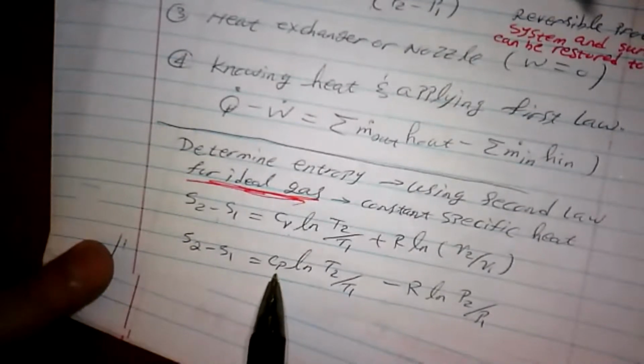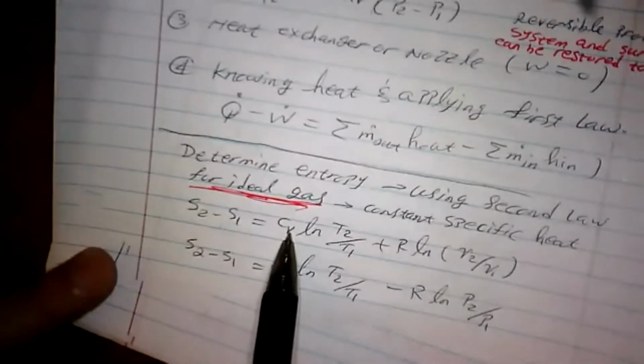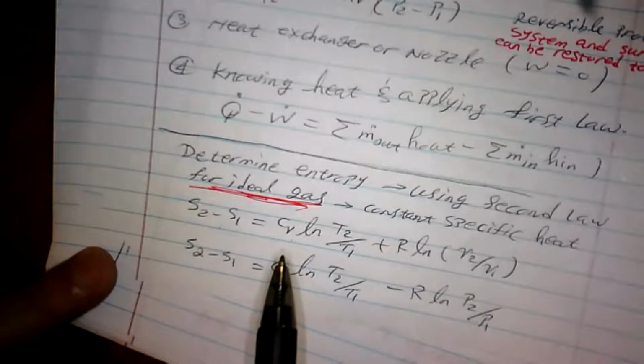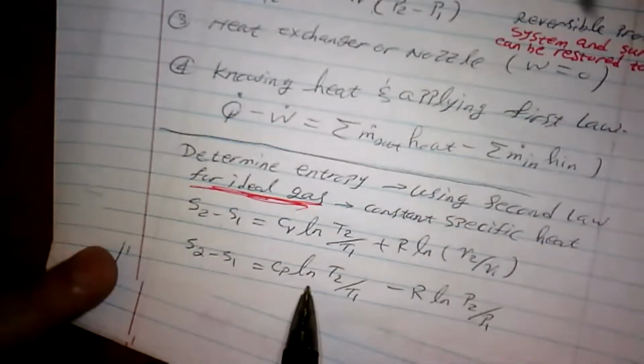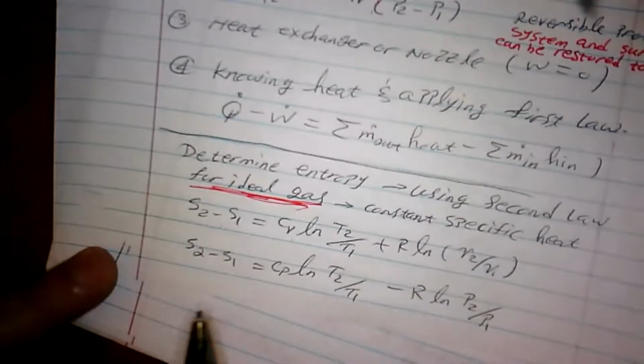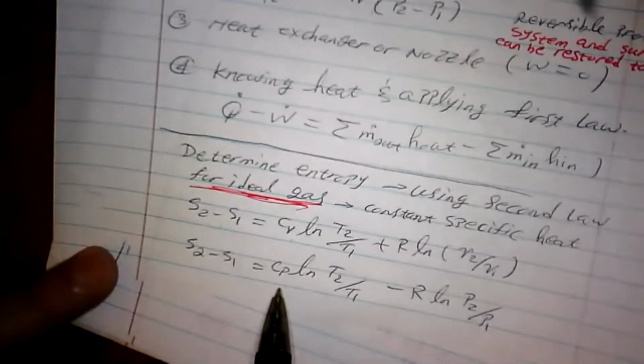It's Cp. You can look that up, okay? You can go to a table, find the Cv for the given temperature or pressure, and determine the Cv and Cp. It's tabulated, okay? It's a table. I'm showing you on the solution to exam one which tables to go to to find the Cv, but we haven't touched on Cp yet. So we're going to be dealing with Cp for open systems.